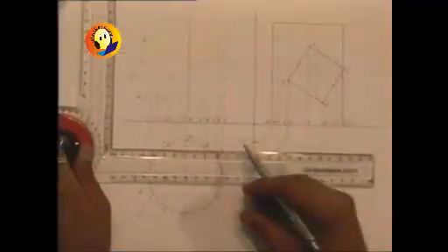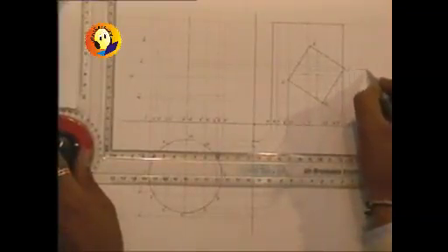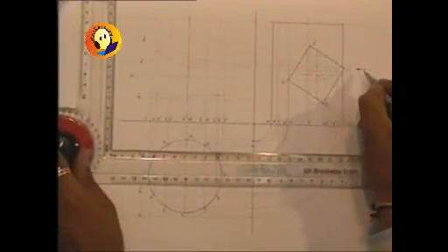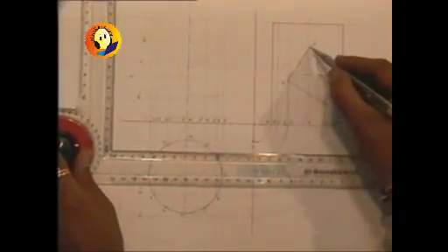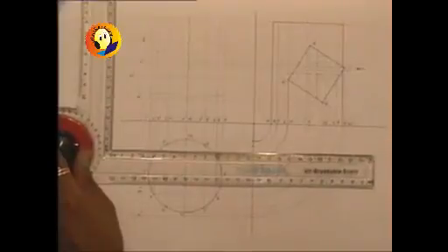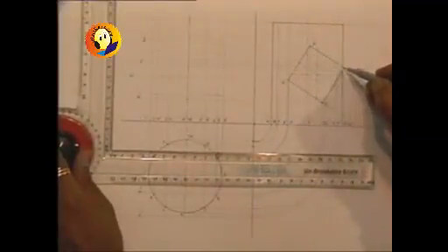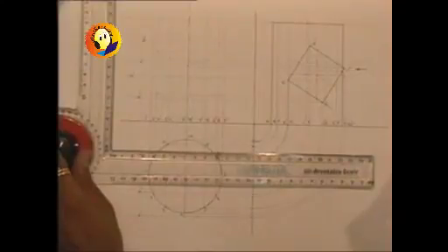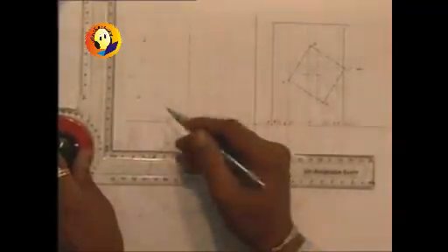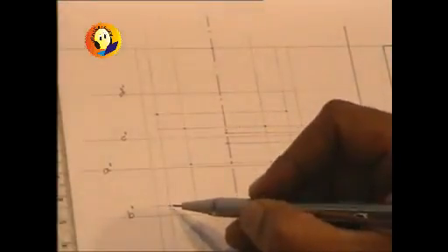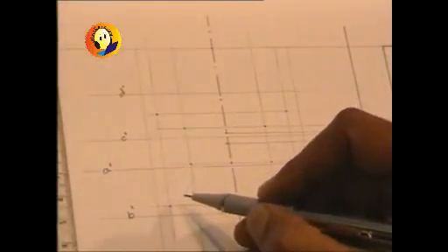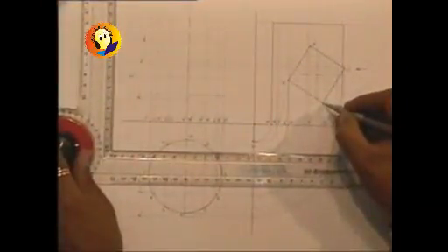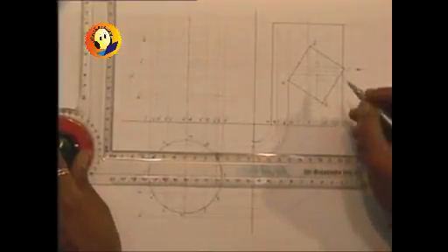next generators are on the back side. So let us talk about them afterwards, because as we are looking from this direction to see the front view, we will be first considering only these faces which we have already considered, because anything that is on these 2 faces will be completely visible, and that's why we will be first joining these points. But to join these points, I will be looking for exactly at what point this particular B dash will be entering inside the cylinder, and for that we are required to take help of the top view.